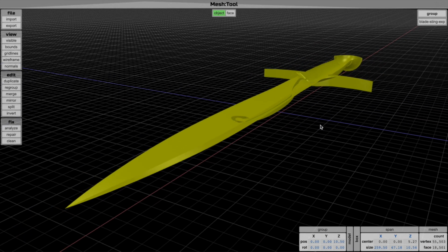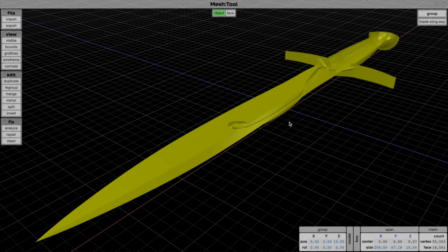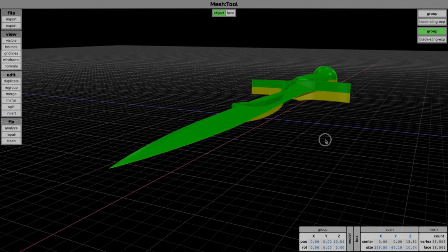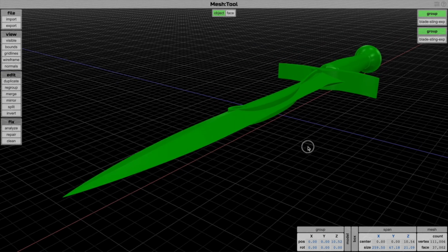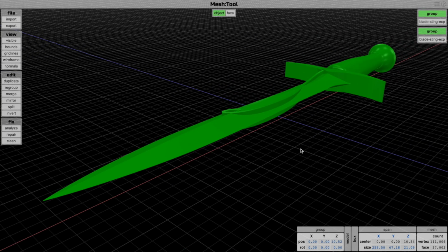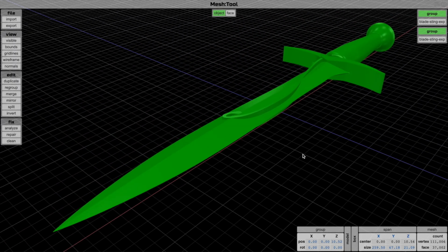And once we have made some changes and we want to turn this thing back into the whole part again, it's as simple as clicking on that and saying mirror. And that will then recreate the top half. And then using the same sort of tricks from the previous video, you can then merge these or export them as a group or as an STL to recompose that into a single part. And that's all I want to cover today.